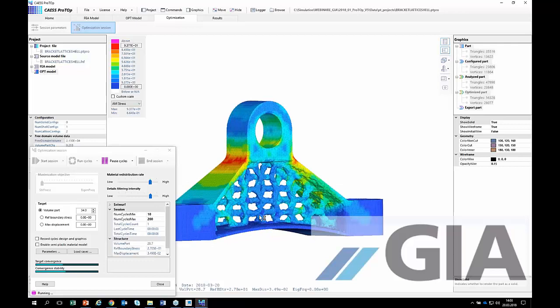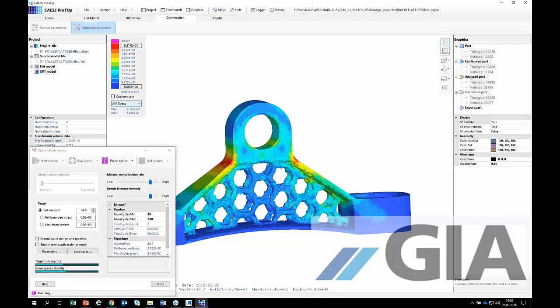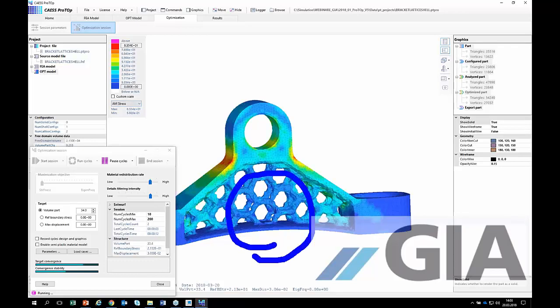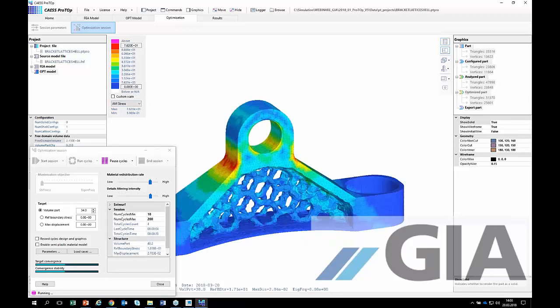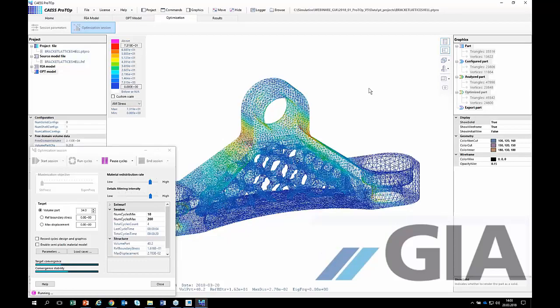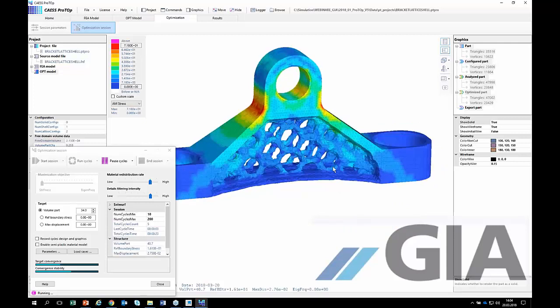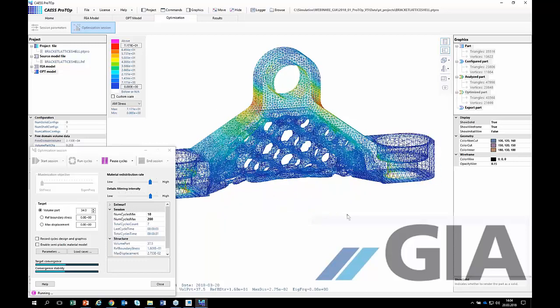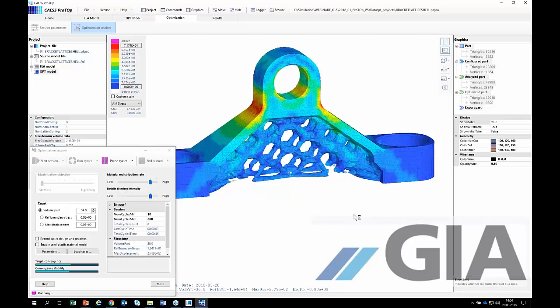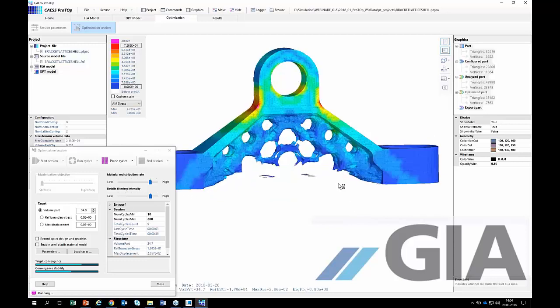34% of the volume. Let's switch here to the stresses, and we can see this area here. There is the low stress area. So ProTOp will take out this area with low stresses, and it will increase only that area with the high stresses. So it's taking out material in that area here. Okay, and the other bars, they're getting thick, thick, and thick. And now ProTOp is taking out the materials in that area. Now we are around 34%,